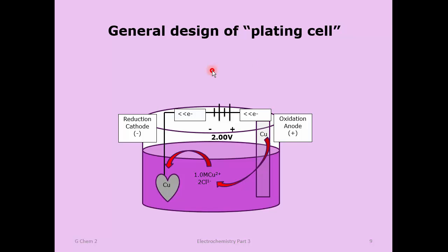One of the key features is that, of course, there's an outside energy source, and I just wanted you to be familiar with this notation in electrical diagramming, where you have the alternating small then large line, and you have multiple ones of these. These represent batteries in electrical diagrams, and every small-large combination represents a single cell. So this might be 2 cells in series, and usually the negative end is associated with the small line and the positive end with the large line.